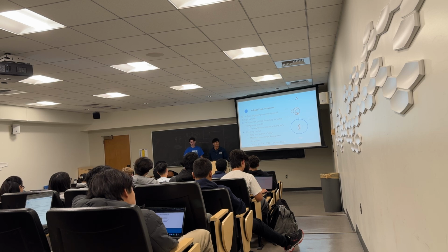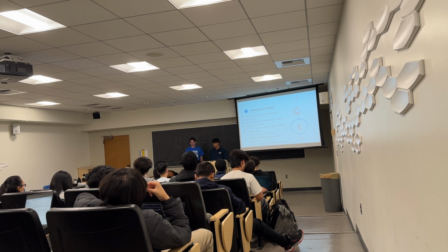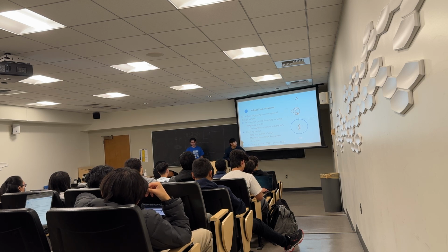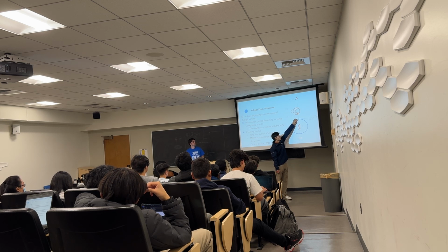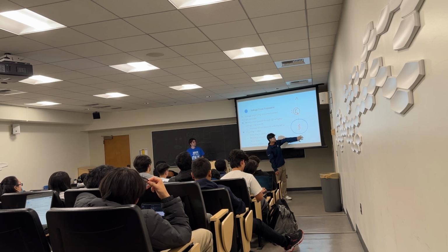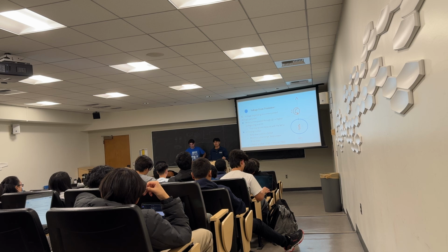Okay, basically, it was what I said, or really what you just said, which is that more current passes through Q1, which is a higher voltage drop over R1, which is what we can measure. Let's see, choosing a value. This is something you guys might not understand. We're taking the output right here, but because this is the voltage drop across this resistor, and since this is ground, it's at 0 volts, whatever voltage is here is dropping across this resistor, and that's what we're taking as the output. But that voltage will change depending on how much current is allowed to pass through, because V equals IR, where I changes, so V also changes.